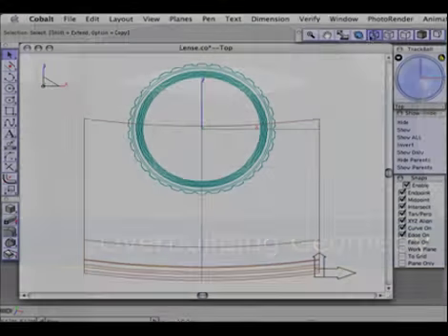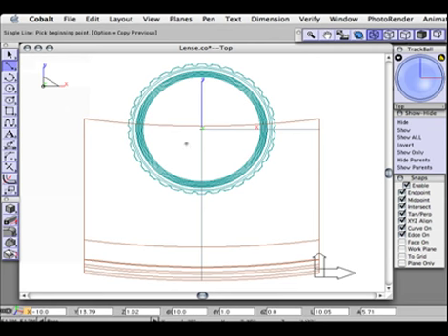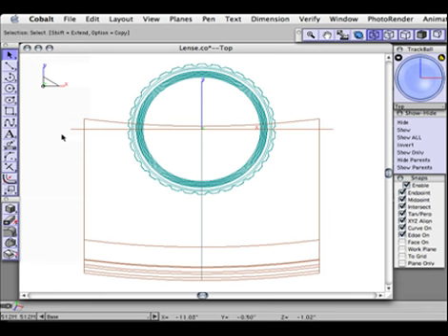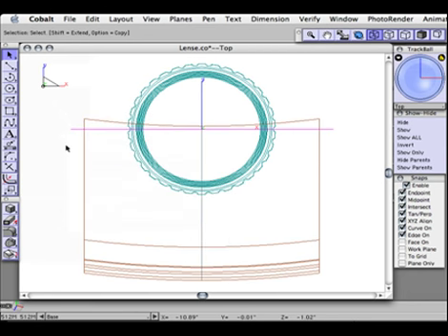Now I want to show you a technique called Overbuilding Geometry. I'm going to cut this solid to be straight, and I'm going to use a line as the cutting tool. But instead of making this line share edges with that solid piece, I'm going to actually make it a little bit longer than it needs to be. I'm also going to go ahead and change the colors. Notice how it extends past the solid a little bit more than it needs to.